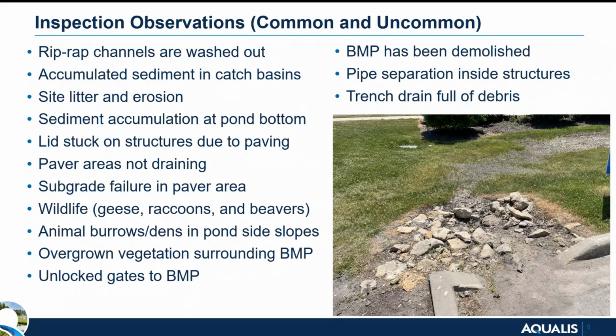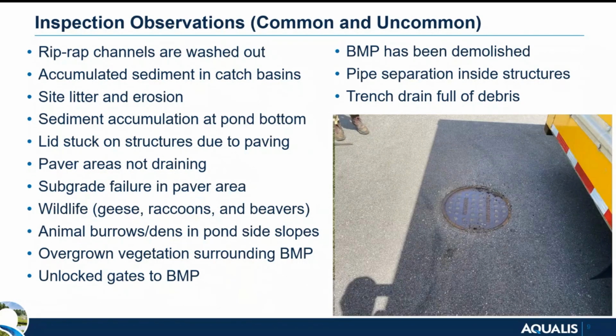A lot of times we'll also see sediment in catch basins, and for our repeat clients, they know to now get those vacked out before they call us, so we don't have to come back for a revisit after they've performed their maintenance. Another thing we've run into is structure lids being either paved over or partially paved over.